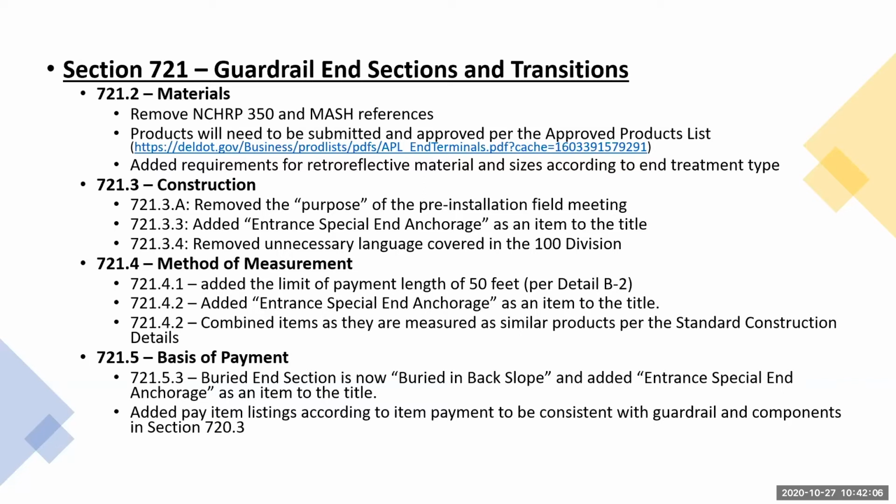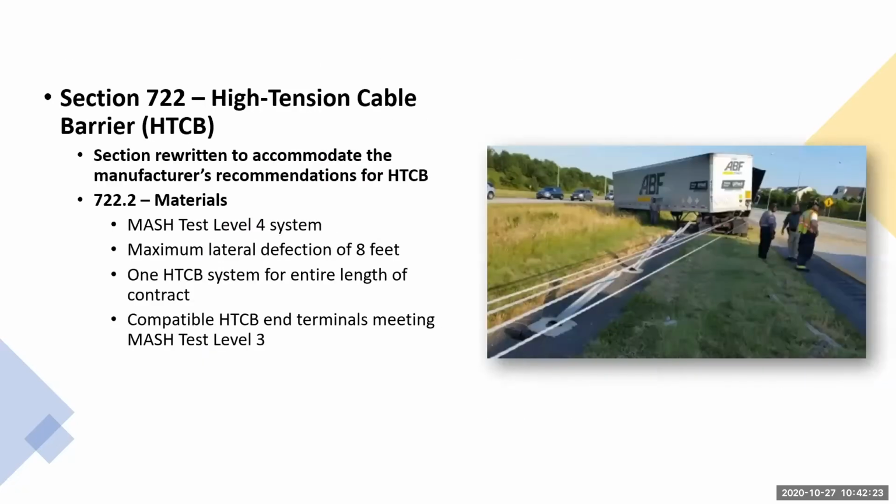We clarified the payment length for the guardrail end treatment, and that's consistent with detail B-2. I'll talk about that this afternoon. The entrance special end anchorage that is in the curb guardrail detail, reference was made to that in section 721 as well.